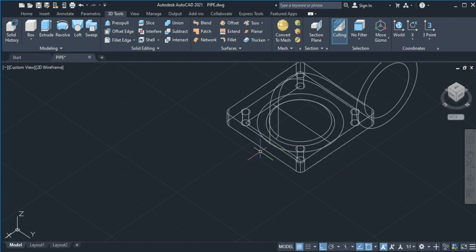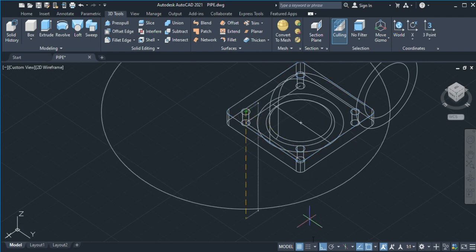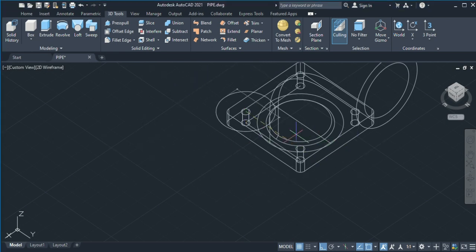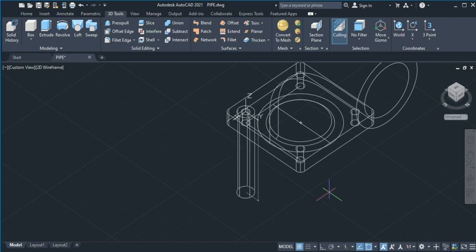And then we do the bigger circle, with the depth of 10. Oh sorry, this is the wrong diameter. I'm not selecting diameter, I'm selecting radius. So change it into diameters and then create a cylinder with a depth of 10 inward.